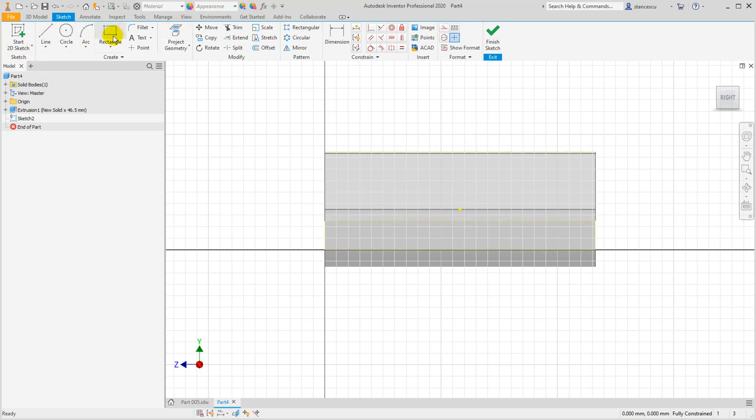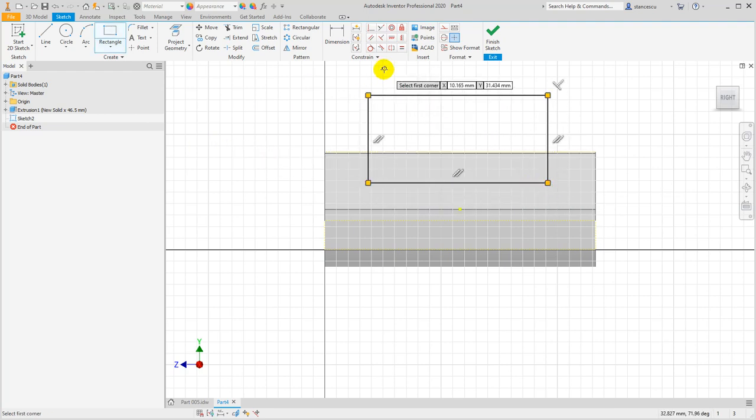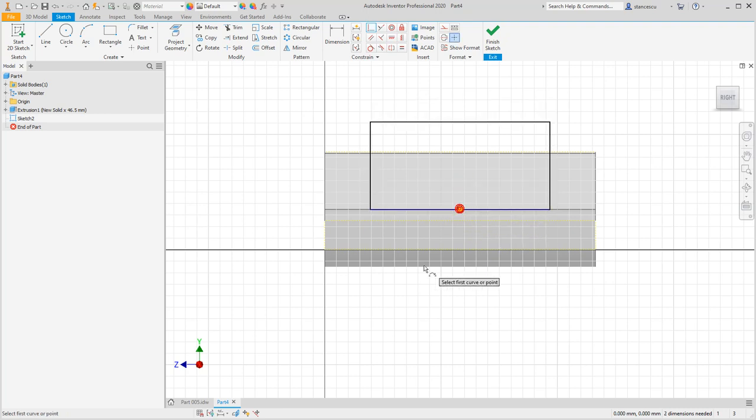Now we create a rectangle, we put the midpoint of this rectangle coincident, not on the same vertical, but coincident with this point, this very point. Good. What means this? It means that the rectangle is symmetrical.